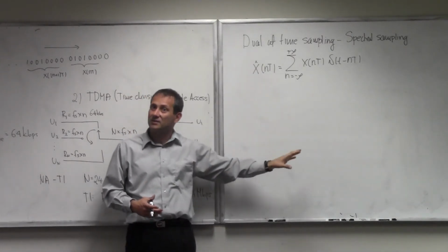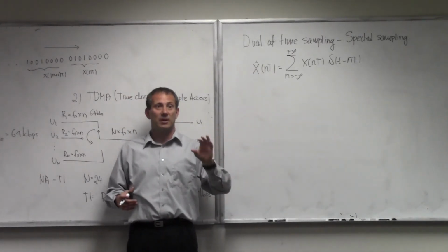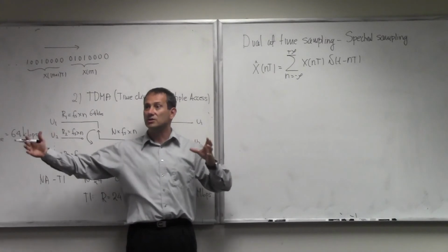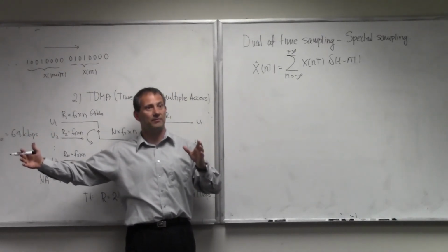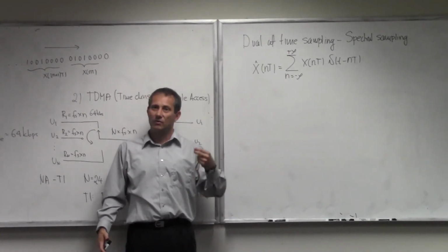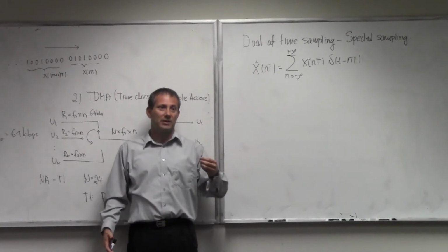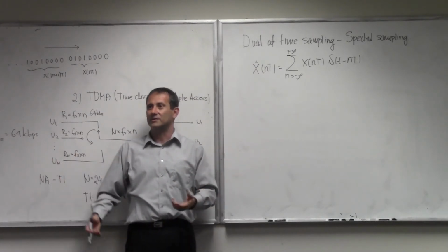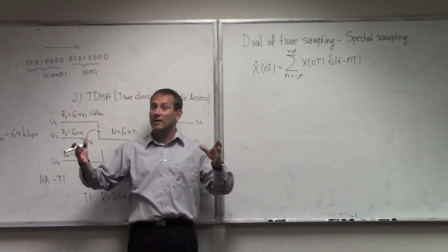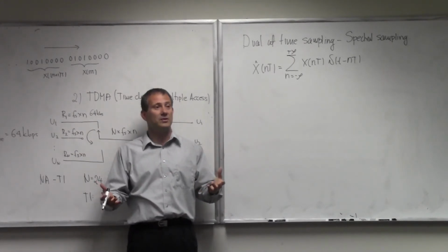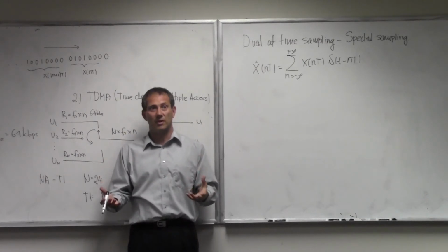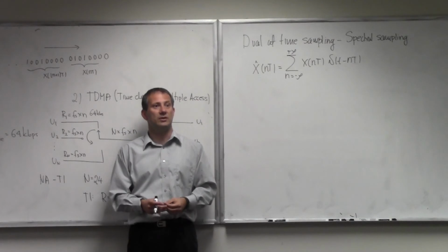What we're going to do over the next couple of boards is talk about determining the spectral content of the signal by looking at just a portion of the signal in the time domain. This is a prelude to something called the discrete Fourier transform. I know we love our integrals and they're all elegant, but in practice, whenever we are faced with the problem of determining the spectral content of a signal, the only practical way of doing that is through a discrete Fourier transform.